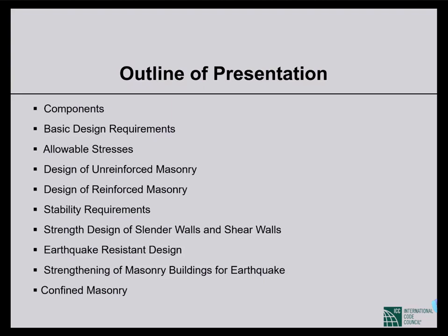But for existing structures, shear strength is very important. For that, we use a different type of test. We use a flat jack, and we take out a brick, or one or two bricks, and we place a jack horizontally. Sometimes it's called a flat jack, and we put pressure on a brick.